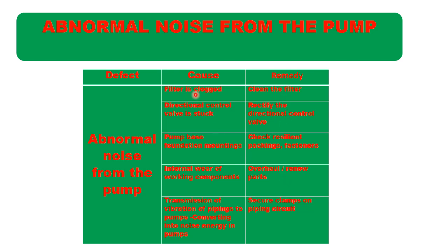First, the filter may be clogged, so clean the filter so that proper oil flow can happen. The directional control valve is stuck, so rectify it; maintenance or replacement has to be done. For the pump base foundation mountings, the tightness has to be checked, and the resilient packings should be in good condition and not brittle after a long time, so replace them if required.